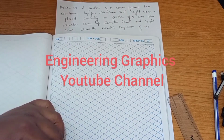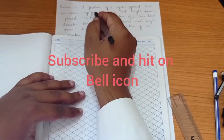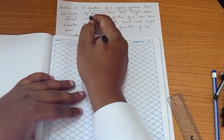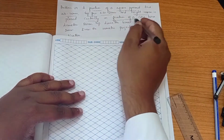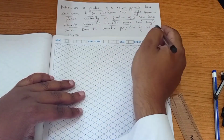Problem number 39 from the CAD solution book. A frustum of a square pyramid, base side 40 mm, top face height 20 mm and height 40 mm, is placed centrally on a frustum of a cone, base diameter 80 mm, top diameter 60 mm and height 20 mm. Draw the isometric projection.